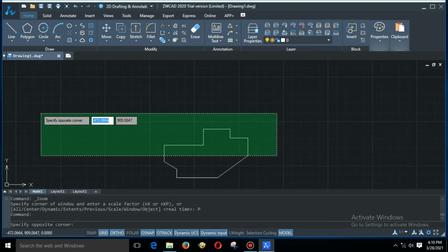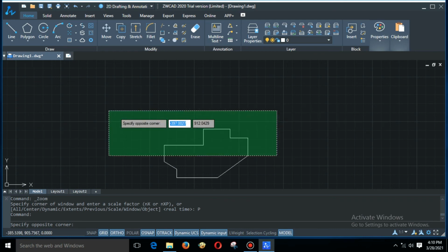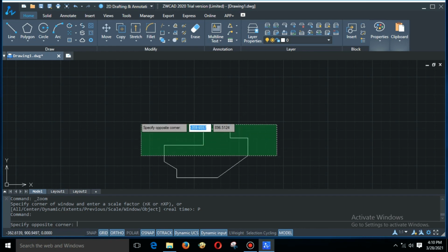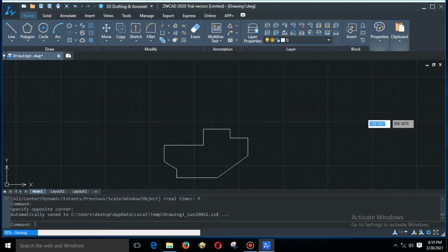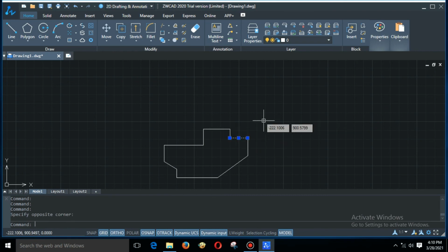Left click and continuously pressing it is for selecting a particular area. Otherwise you can just click normally to select one singular complete figure, which can be a line or a complete drawing. But you can see this drawing is not one singular polyline, right? You can draw this with a polyline too, mind you.